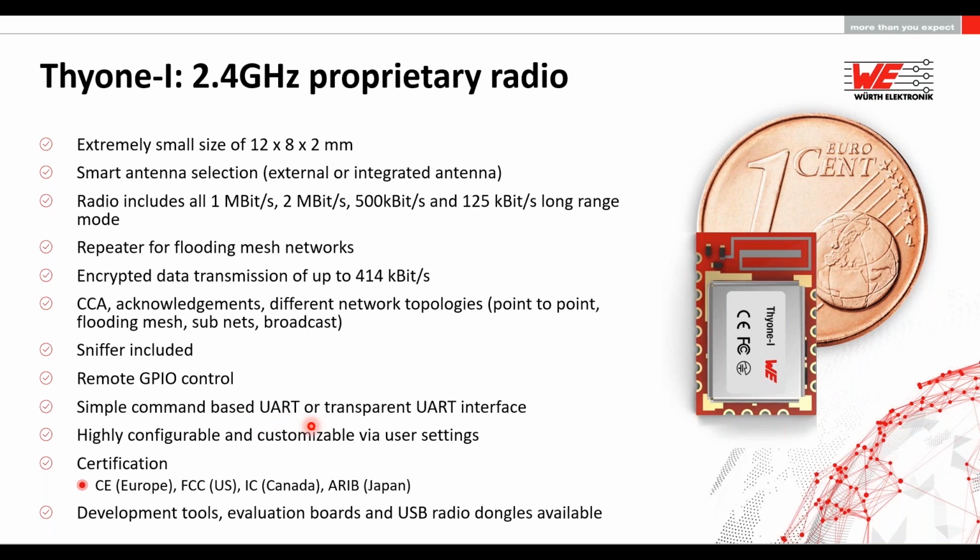Like I said, the module comes typically with a standard UART interface and a transparent UART interface, which is interesting if you have a device which is already using some kind of RS-232 or RS-485 serial communication. This Thyone-I can be a drag and drop replacement for your wired connection. So keep this in mind. This is really interesting. Not to forget, all our modules, including the Thyone-I, are pre-certified to be operated in Europe, US, Canada, and Japan.